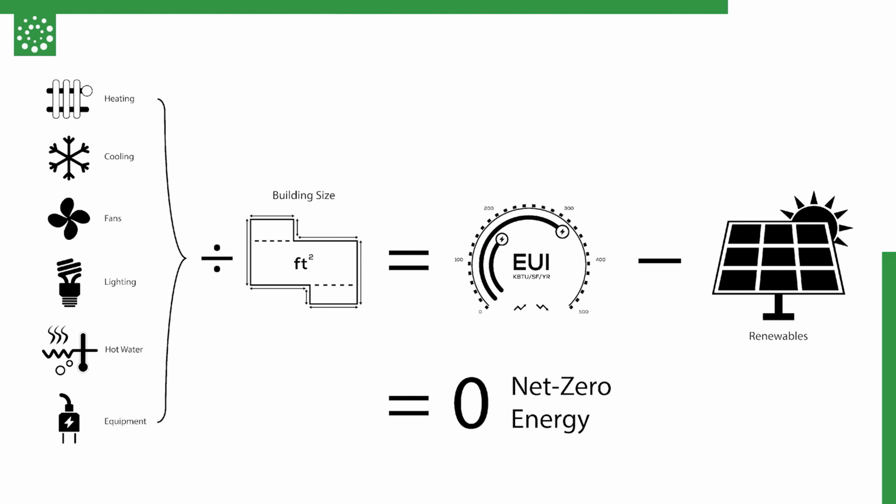But if you design your building high performance, you move that down, and now you're purchasing, say, 25 EUI of renewable energy and operating your building at a 25. And that's really how it becomes affordable to create a zero energy building. It's about drastic energy reduction so that you can afford the renewable energy or the PV to offset that.